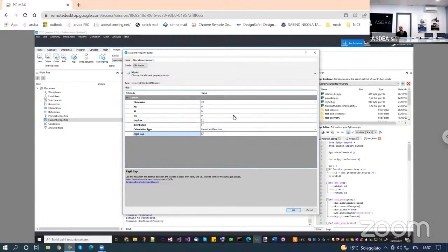So this one is the typical setting that I use if I have to create contact of a pile in a soil. So I create a hole which has the radius of the pile. The pile is modeled as a beam, and then I create this sort of contacts between the beam nodes and the nodes on the soil domain. For you, it's the same, but it will be from the beam to the shell. It will be much easier because the direction is taken automatically from the geometry, not from the local axis you provide. So it will be much faster for you. And it will also be slightly more correct because it takes into account the thickness of the beam. Okay, that was very helpful.